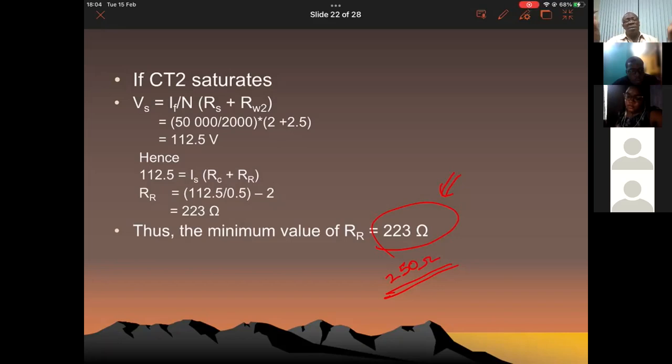Okay? So you have the true fault. If the true fault causes saturation, no problem, because you are using the high impedance differential circulating current scheme, right? And by putting in that 250, the current will pass through the transformer, continue to the fault. The differential protection on the transformer will not operate. But you would limit the current on the transformer by using your overcurrent relay. Is that clear?